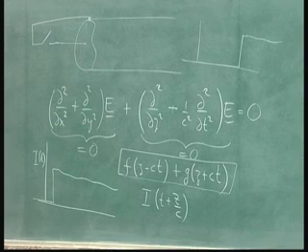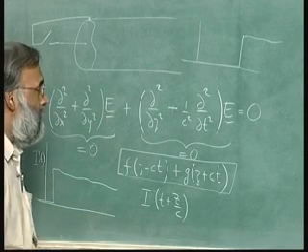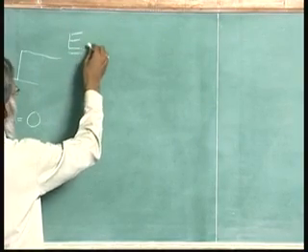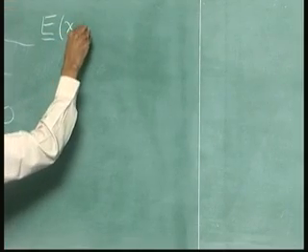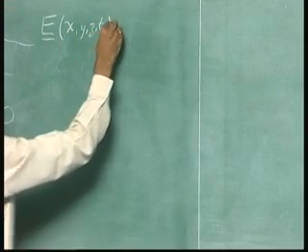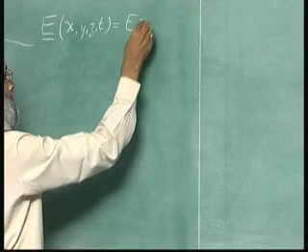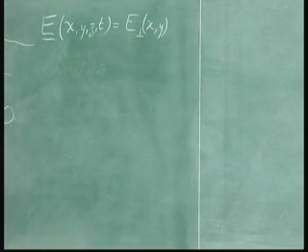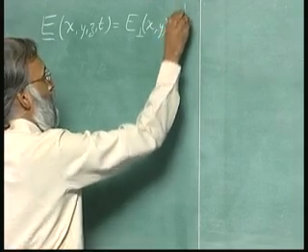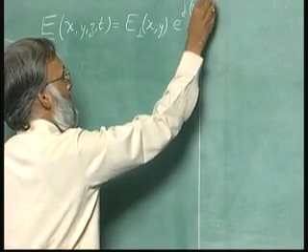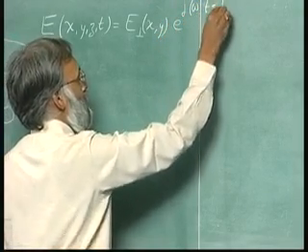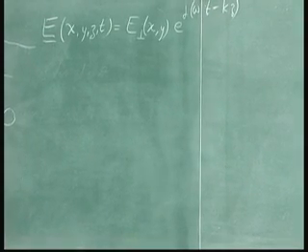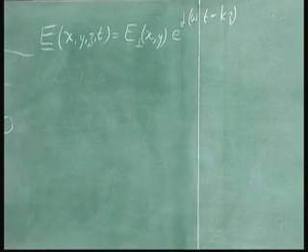And as we saw last time, the way to solve this problem is to look for solutions of the type: the electric field, which is a function of x, y, z and t, is some perpendicular function, a function only of x and y, times e to the power of j omega t minus kz. Of course, it can also be j omega t plus kz.